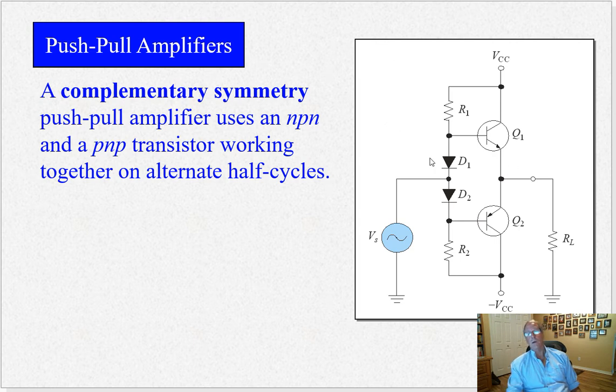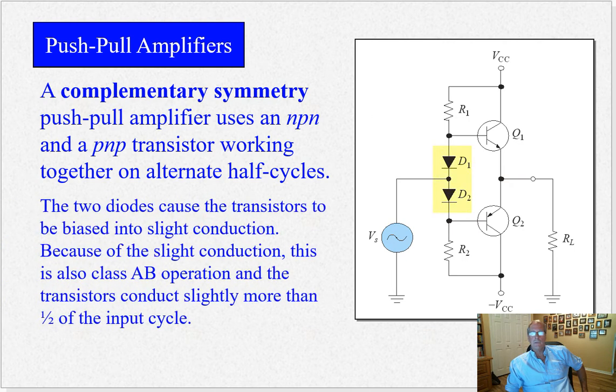And this is a lot more typical, honestly, for a Class AB amplifier. And we use these at work to drive audio lines long distances. We put a little snubber out here, a little inductor and resistor combination. But this is a real common, nice circuit. It's very low distortion. It produces an AC waveform that is very, very close to the input waveform. And it's very linear. So that's a good amplifier right here, this Class AB complementary symmetry amplifier.